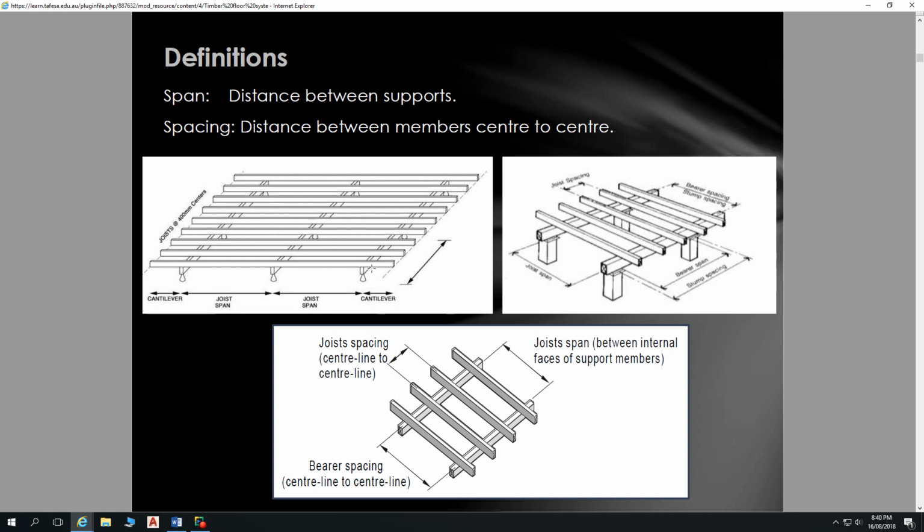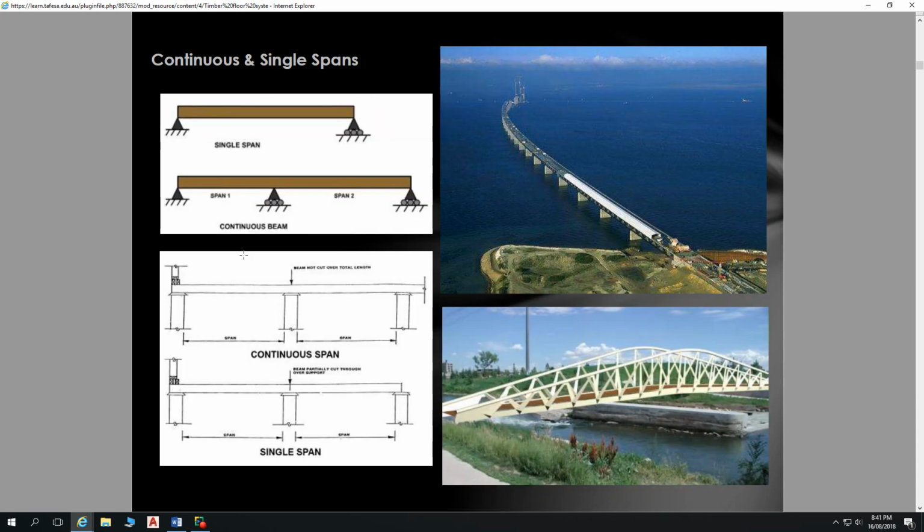And so those joists, technically they're spanning slightly less than 2 metres. They'll be spanning 1910 millimetres, so less than 90 if we've got 90 wide bearers, or 1955 spans. But typically we'll just calculate our spans as being 2 metres. That makes sense to everybody, spacing versus span.